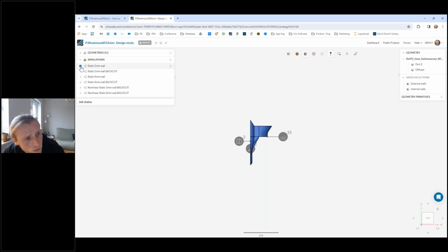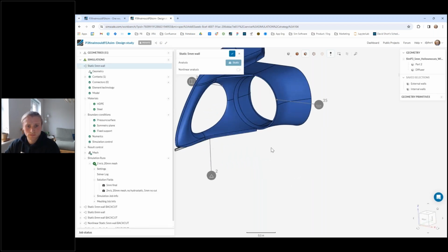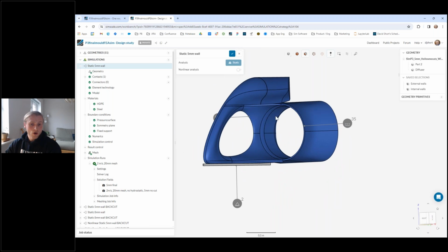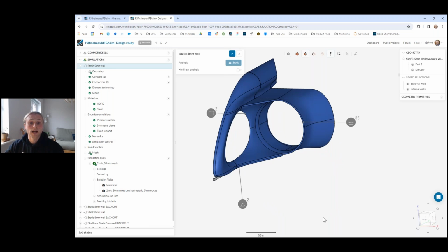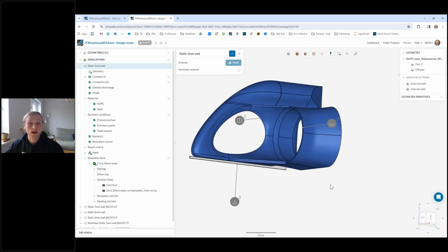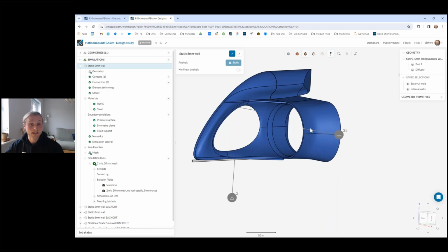So what we have had a look at are some different scenarios. We've got Energyfish design number 1. We've taken out the turbine for now because that's not our area of interest. What we're really interested in is the maximum deflections and stresses within the plastic part itself, so the actual hydrodynamic casing and shrouding around the turbine.